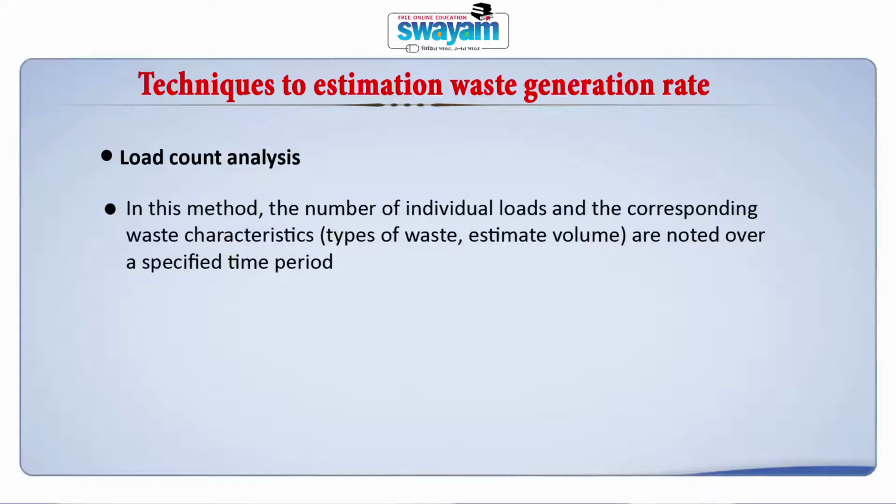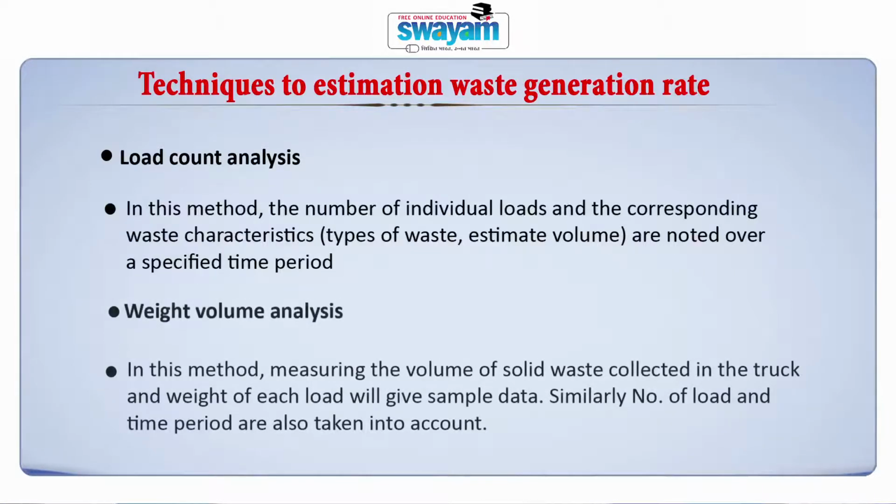In the load count method, the number of loads a particular collection vehicle or truck is carrying is noted down, along with the weight and the waste characteristics, and with that the load count analysis is done for a specified or stipulated period of time. Now, in the weight volume analysis, the volume of solid waste collected in the truck is measured and weighed for each load, and then the amount of solid waste is calculated based on the number of loads, weight, volume, etc.